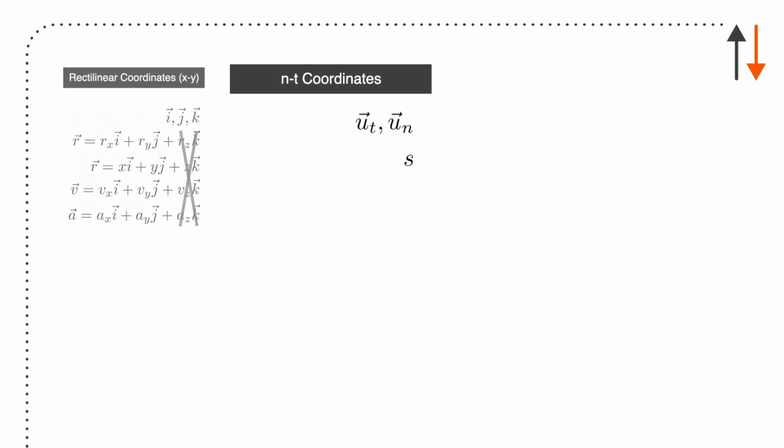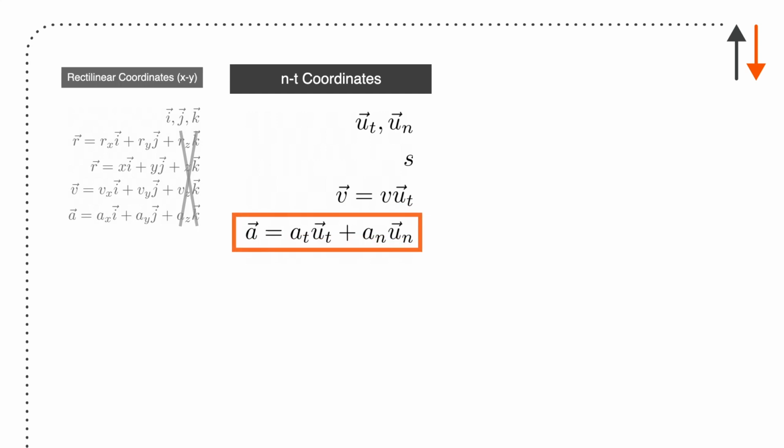In terms of the second coordinate system, the main thing is here we have position, which is defined as the magnitude along the path, and that's it. It's not a vector. It's not really used at all in terms of problems when you see this in the course. You just get velocity or acceleration. So what makes that easier is that now when I want a velocity, it's just the velocity acting in the tangential direction. Acceleration is acceleration acting in the tangential direction.